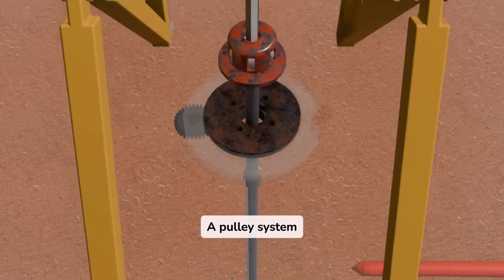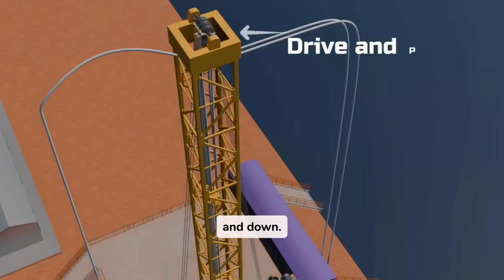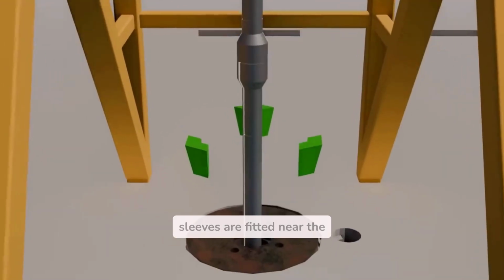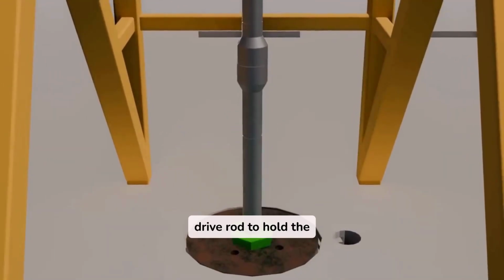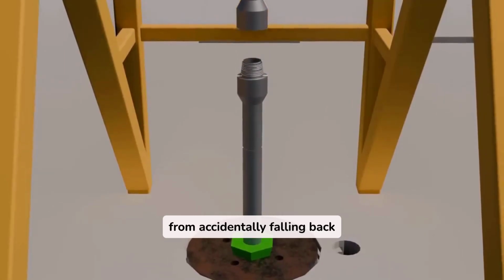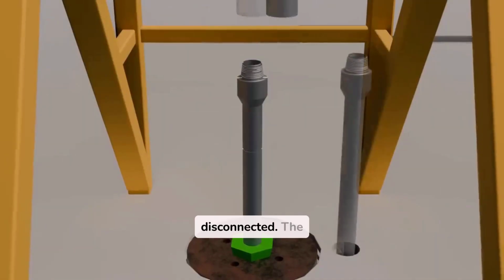A pulley system is used to move the Kelly rod up and down. When the Kelly rod is completely out, sleeves are fitted near the drive rod to hold the drill string securely. These sleeves prevent the string from accidentally falling back into the borehole when disconnected.